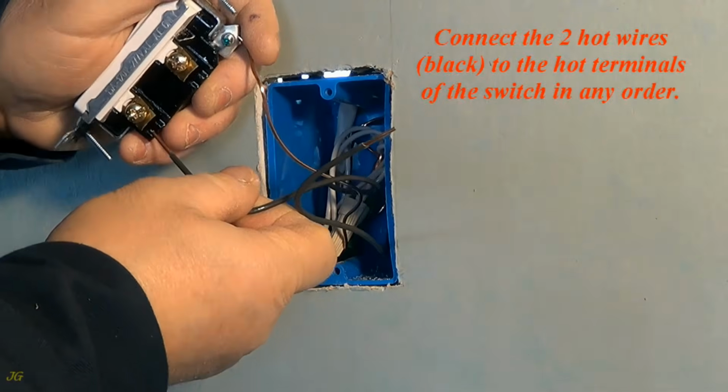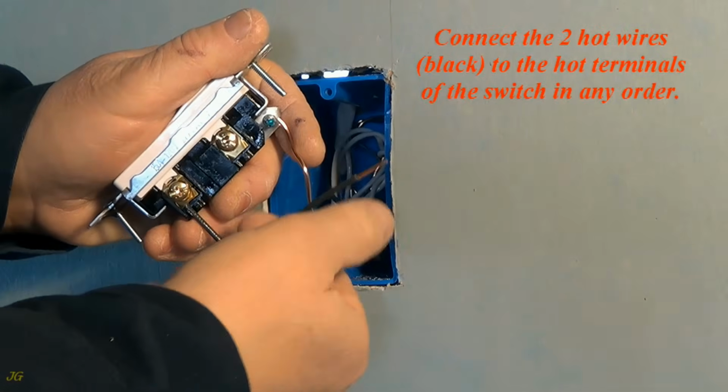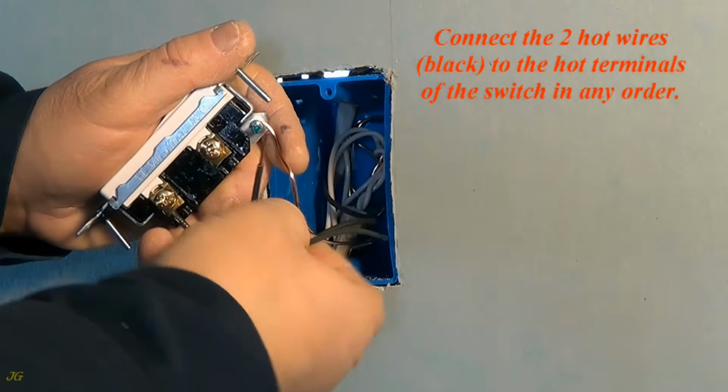Connect the 2 hot wires, black, to the hot terminals of the switch in any order.